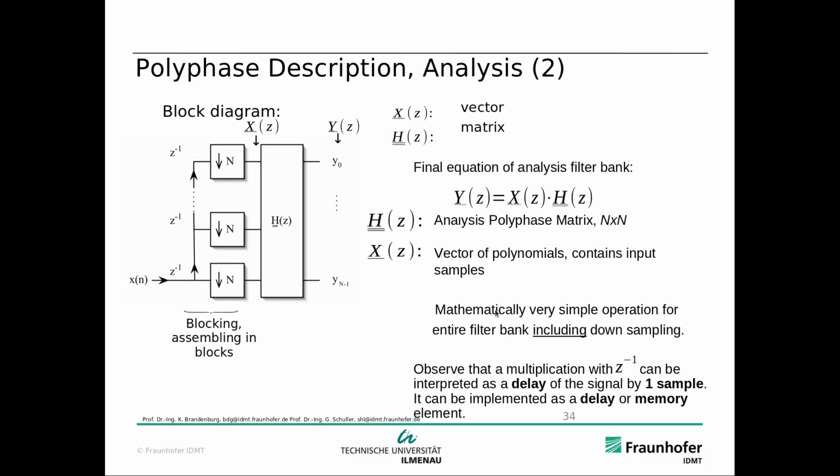Yeah, and this is the resulting block diagram of the analysis filter bank. Now with the polyphase implementation, here we have the blocking, the assembling in blocks. Then here we have the polyphase matrix, and out comes a set of subband signals in the Z domain. Right? And mathematically, that's the important part, is really easy now.